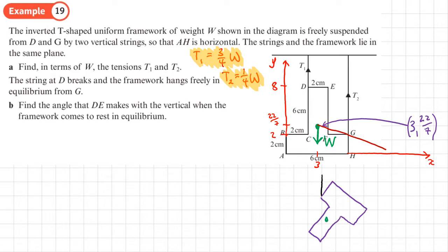What's important is that that center of mass needs to be directly below the point at which it's freely suspended. So I just need to make sure on my diagram that I draw a line going through G, through the center of mass, and I've put it on here, so I'll maybe draw that a little bit more clean and draw it for you again. So center of mass going through the point that it's suspended, which is here, and then I'm going to be using some trigonometry to work out what that angle is. So I'll just tidy up those things a bit.